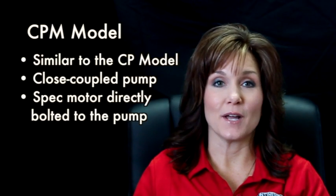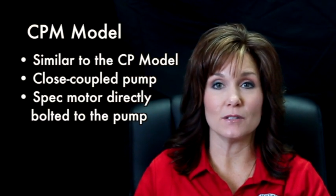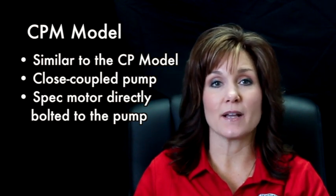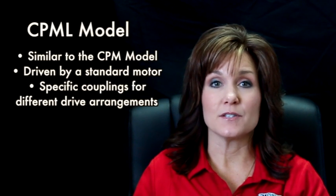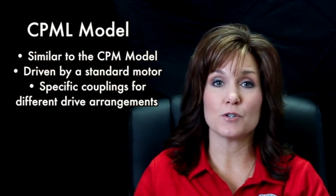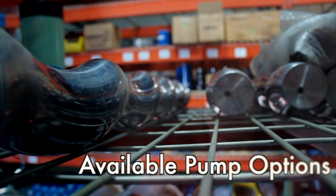The CPM model is similar to the CP model, except it is a close-coupled type pump that is driven by a Continental spec motor that is directly bolted to the pump. The CPML model is similar to the CPM model, except it is driven by a standard motor attached by a specific motor coupling for different drive arrangements.